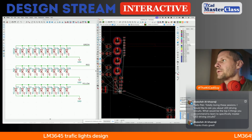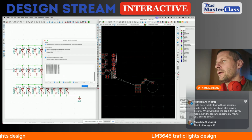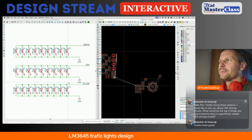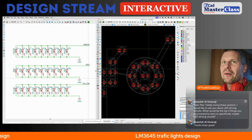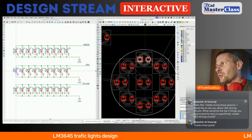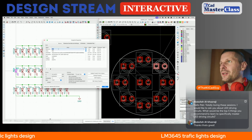So when I update, no, this is not what I wanted. Yeah, do you know what happened? The new LEDs were removed because they have representation in the schematic. So now I have to assign the reference designators as I mentioned earlier.